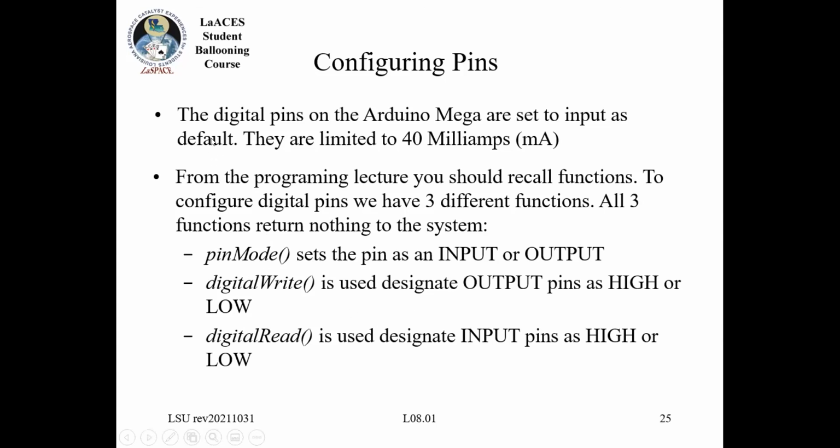Now, I did just say they default to input, but even if you're using the pin as an input, I would recommend you include the appropriate function call to make sure that it's set to an input, right? You always want to have a positive control where you have defined the state that you want it to be in.